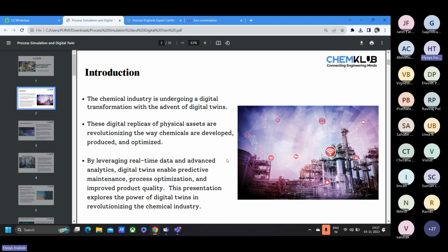For example, they can be helpful in predictive maintenance. Say your compressor is getting tripped, for example 5 to 6 times in 6 months. With the help of simulation models, we are simulating the process parameters, and with advanced analytics, we are seeing how frequently it trips, what the mean time between failures is, and why it is getting tripped. Some parameters will have a correlation matrix with each other. So in a way, it is helpful in predictive maintenance also.